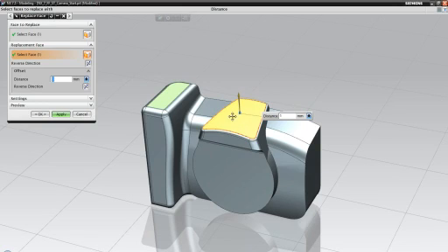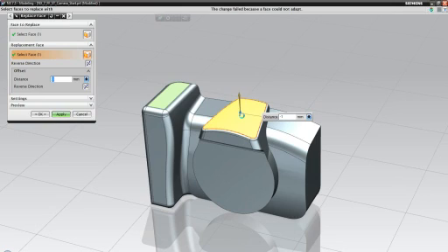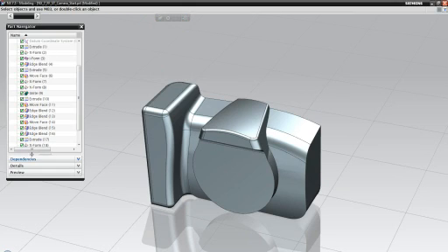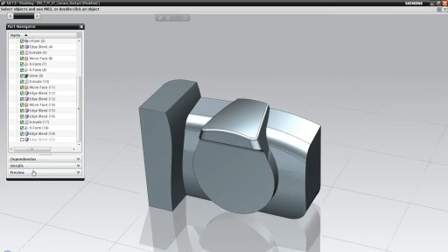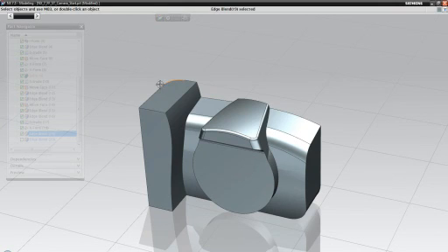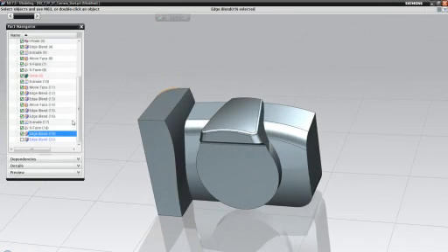You can kind of see that I'm going to get in here. I probably should have done this before I added these rounds in, just to have a little bit more control, a little bit better shape off of that feature. What I'm actually going to do is come back in here and just suppress those blends for a second. I'll add those back in a minute here.